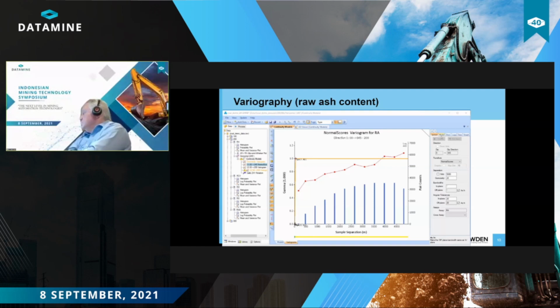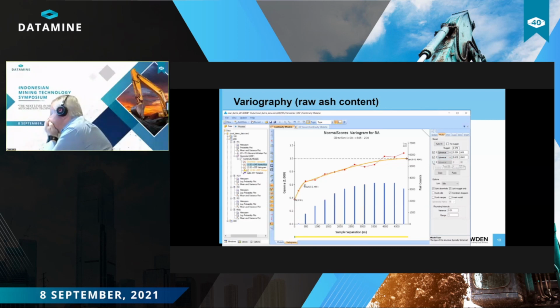If we go to the Model tab, we can click the Auto Fit button and just see what we get. We can choose different model types here. In this case, the default is spherical. In this case, it's used two spherical models to model the data. We could try adding a third to see if that would improve the fit at all.